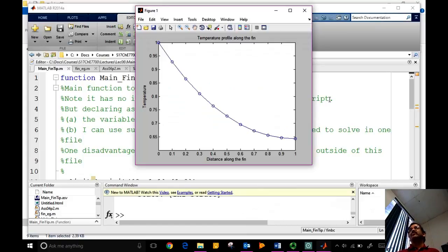So that's easy. If you do it analytically, it will take another half an hour. You can solve it because it's still linear, right? But what you see here is that the tip is hot now. It's not at T infinity, right? The tip is hot, but the gradient is 0 because it is insulated physically. So there is no way for the heat to be lost, right? Now, if I want to still drive this temperature to 0, what can I do?